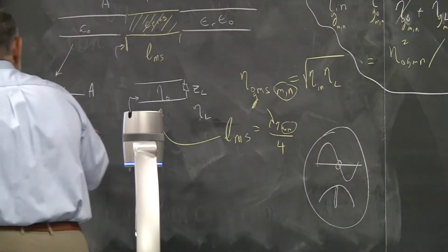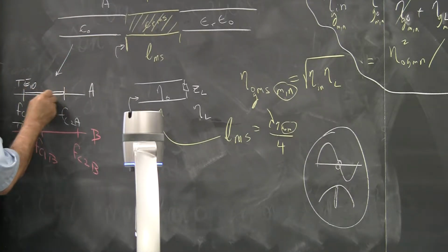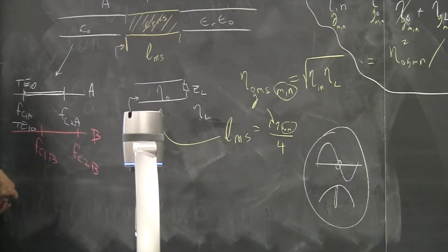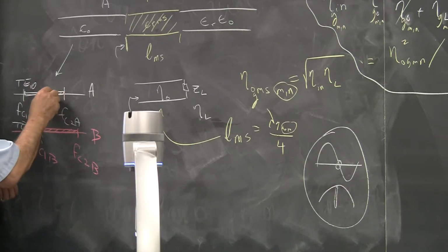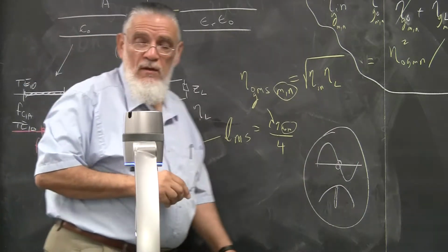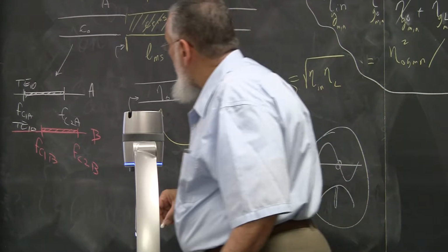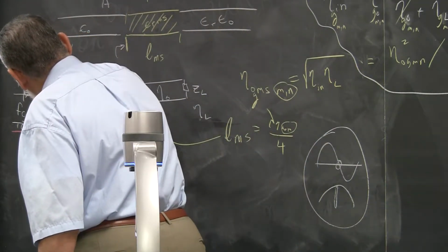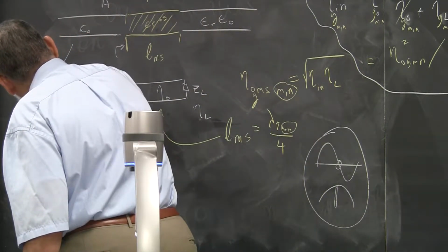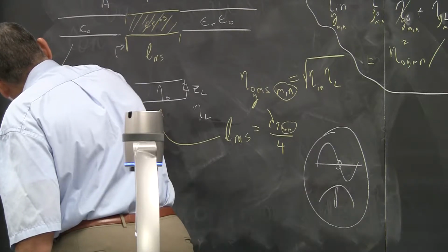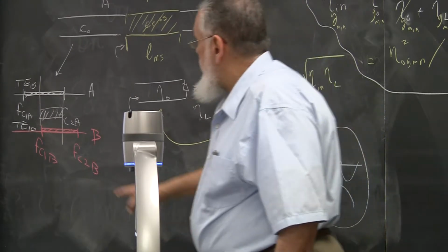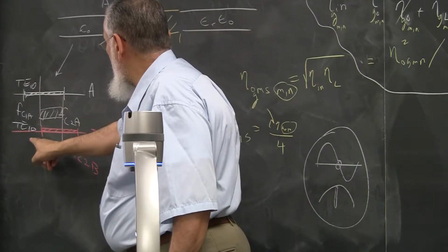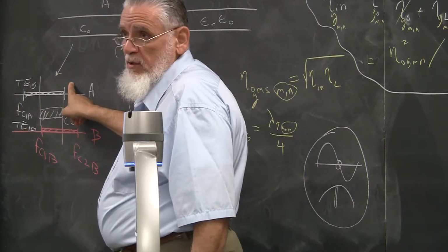So that's the same mode. That's your TE10 mode right there, this region here, and the TE10 mode for the other guide is this region there. So obviously, your region of common operation is this region here. That is your region of common operation between the two guides. You don't want to go that far, this guide will be cut off. You don't want to go that far, this guide is multimodal.